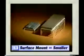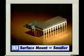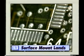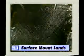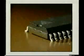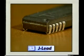Surface mount integrated circuits often look similar to their through-hole cousins, but are much smaller in size. Surface mount ICs also have leads designed to sit on the printed wiring board rather than being inserted through the board. The most common surface mount leads for ICs are the gull wing and the J lead.